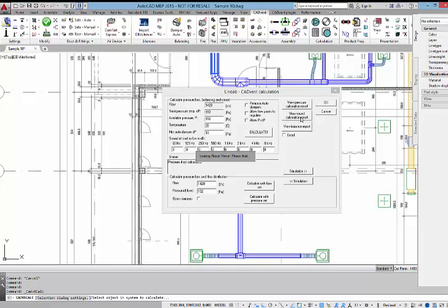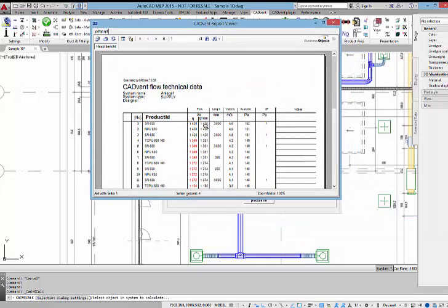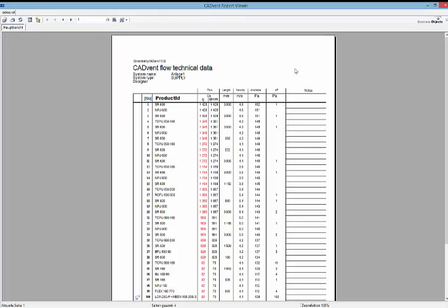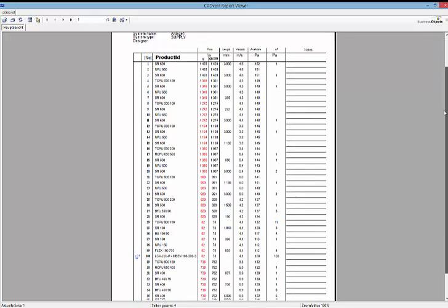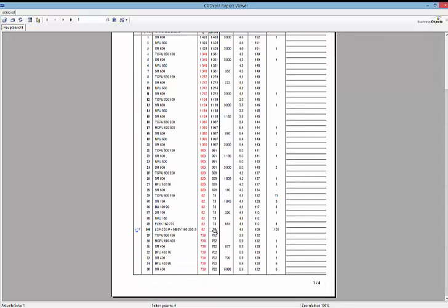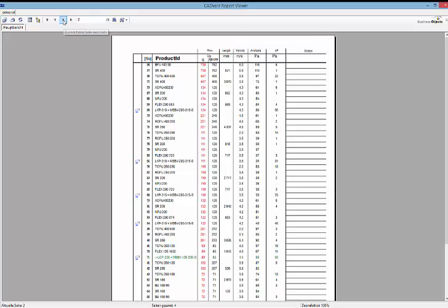When the pressure result is popping up, you will see that there's two different information. There's a nominal flow and there's a real flow. And the difference is coming from the non-balanced system. So we'll see instead of 78 liters per second, we get 82. And there are multiple pages now, and you can see immediately on each device how much influence will sizing have or not.